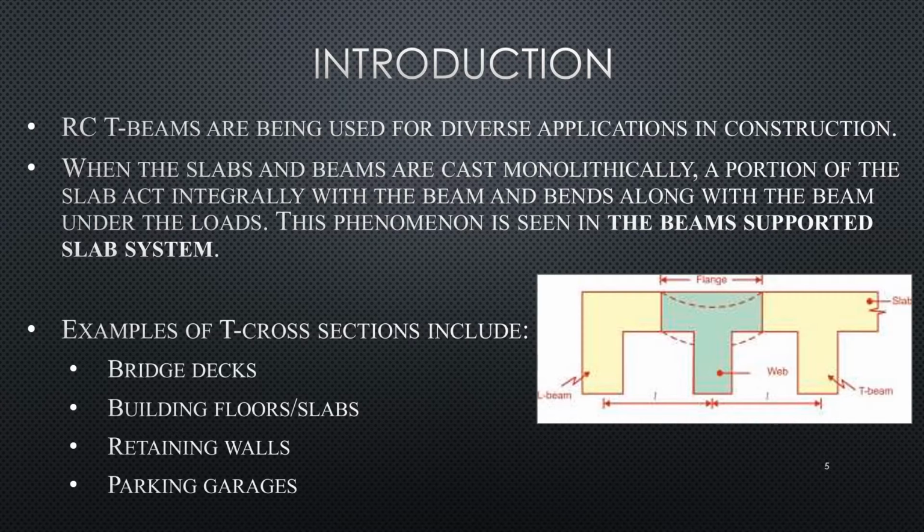Reinforced concrete T-beams are being used for diverse applications in the construction industry. When the slabs and the beams are cast monolithically, a portion of the slab acts integrally with the beam and bends along with the beam under loads. This phenomenon is seen in the beam-supported slab system, as you can see here in this figure. Such examples include bridge decks, building floors or slabs, retaining walls, and parking garages.